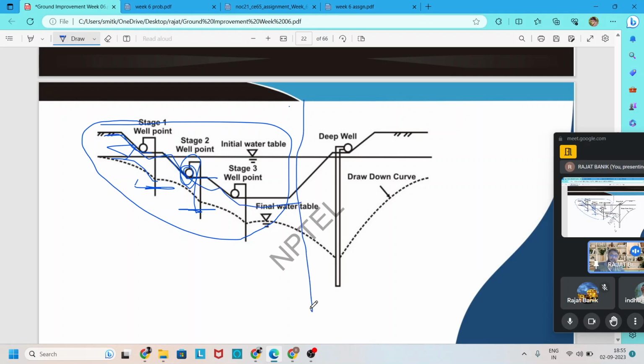we incorporate another dewatering technique, that is the deep well submersible pump technique. So here one high powered pump is incorporated below the pipe. After that, a pipe is attached to this pump, and like that water gets collected from here, and the original groundwater table may be reduced by this one arrangement only.